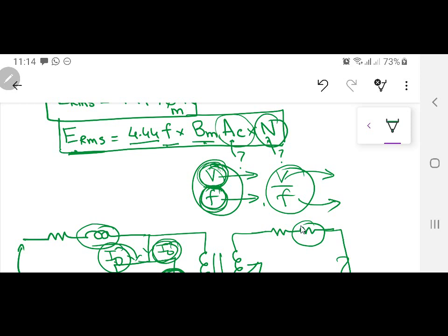How? क्योंकि ये इसका conductor मोटा है, इसमें current ज्यादा है। This side has a larger thickness of the conductor, so this means certainly the current capacity is more. So when current capacity is more, this means that it is the low voltage conductor. This side, the cross sectional area is small, so here the voltage is high, ठीक है। हाँ, अगर it's a 1-to-1 ratio transformer then certainly I can't tell, but since this has a step up or step down, अब क्योंकि I know this transformer is a 220, from this side 220 to some 48 volt or 50 volt something over here, so I know what is the low voltage side.